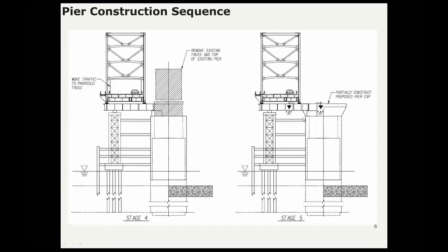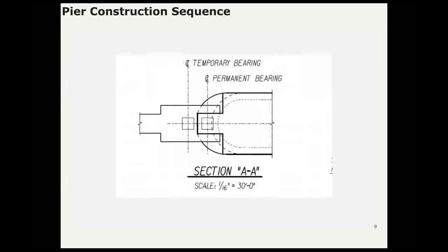The sliding girder is shaped like a tuning fork at this end. It widens out and misses the middle part of the pier cap to make the slide possible. And the next slide shows that in plan view. You can see the sliding girder coming over. It's got two beams that are attached onto the main girder that bear over on the sliding girder pedestal, which is part of the pier cap.